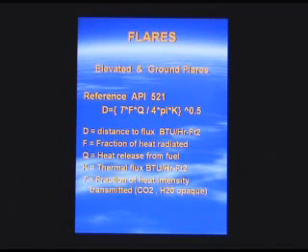So if you have a light hydrocarbon, 20 molecular weight or less, and your factor is 0.1, that would say that only 10% of that flame is converted into radiant energy, which is then distributed out as a big sphere within that region.